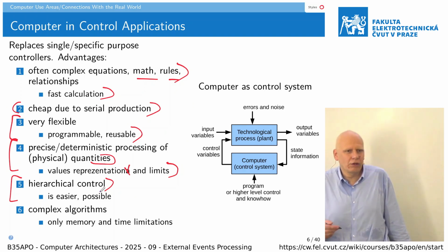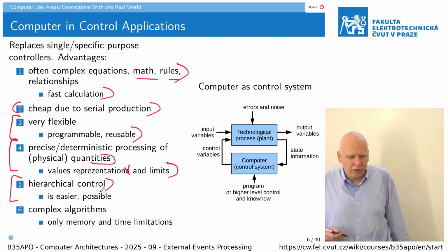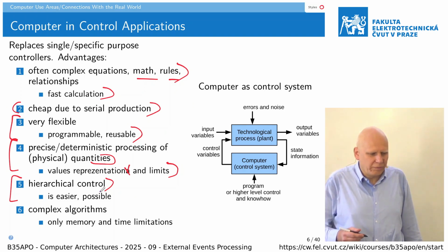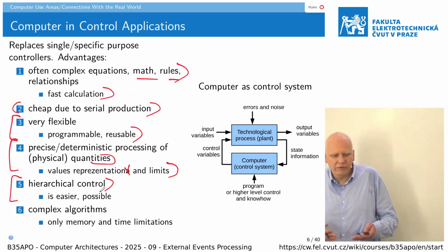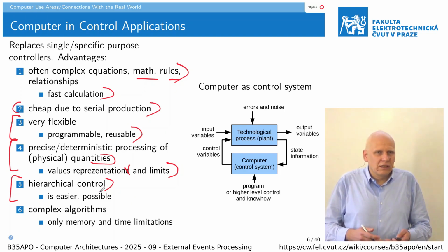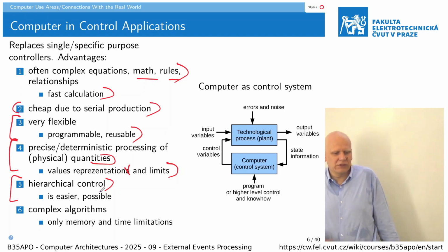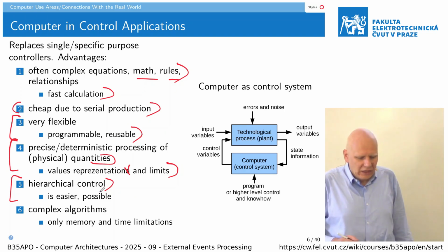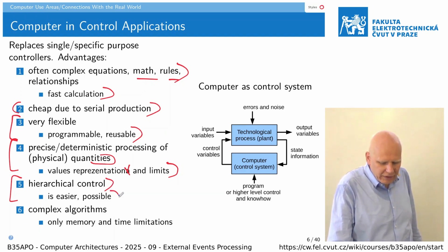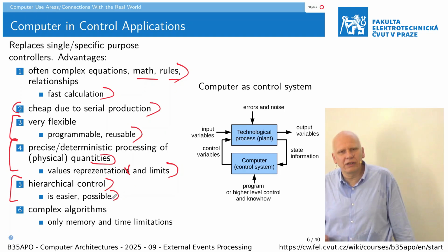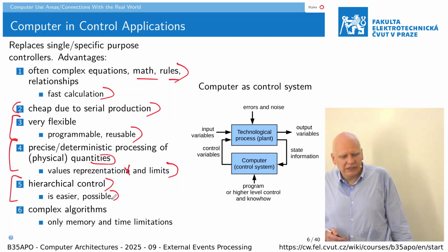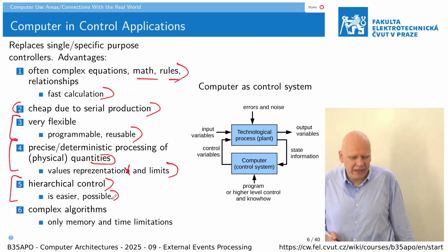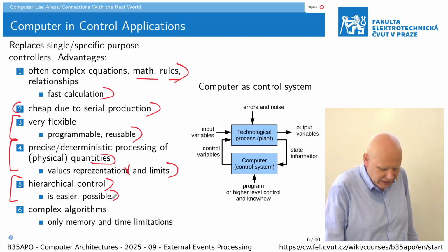On the low level, a brushless or permanent magnet synchronous motor requires something like 4 or 20 kilohertz sampling times or sampling frequencies. But on that higher level where you process, for example, some camera data and so on, something like 25 hertz or something like that is enough.